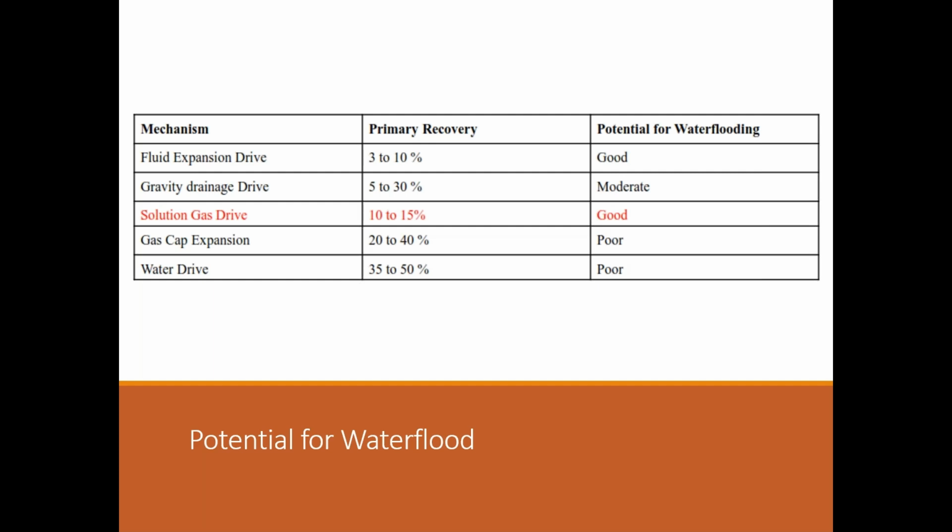As you go on reducing the drives, if you go to only fluid expansion drive, you can expect a recovery of 3 to 10%. But generally, in any reservoir, there is a combination drive. A gas cap is present somewhere, water is present somewhere, and somewhere gravity also plays a role. So the primary recovery that we obtain is a combination of all these, and we get a mixed kind of recovery. So you can see there is potential for water flooding.